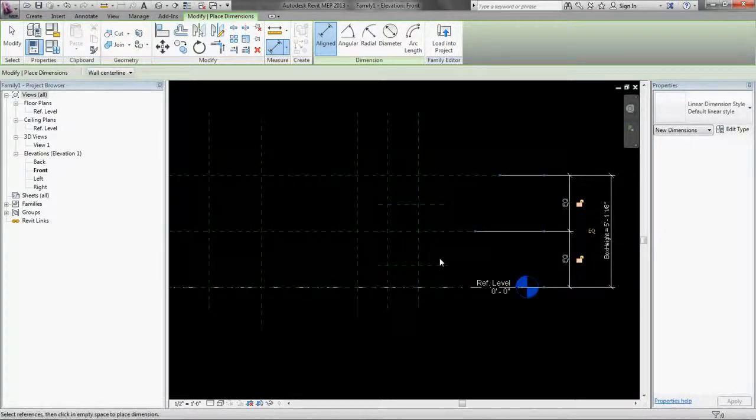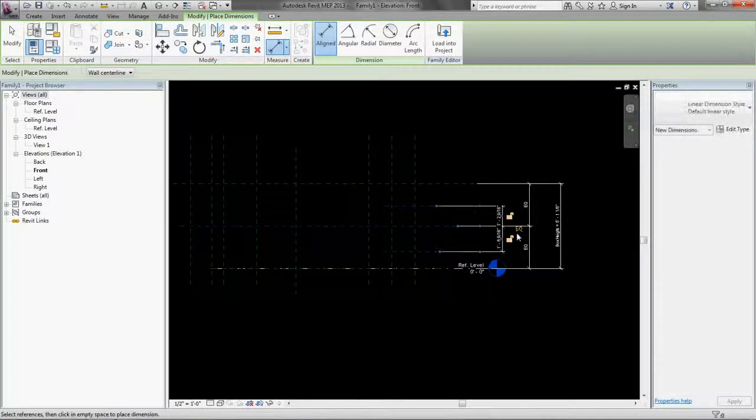And now these two pipe connections. If I was working off a cut sheet, I would maybe look that up and set them to whatever they are based on the cut sheet. But again, this is a generic family, so I'm just going to make it simple on myself. I'm going to set them equidistant, symmetrical around the center line, if Revit will let me do that.